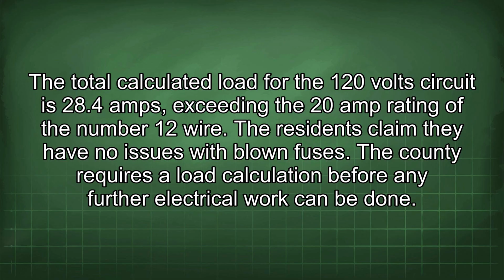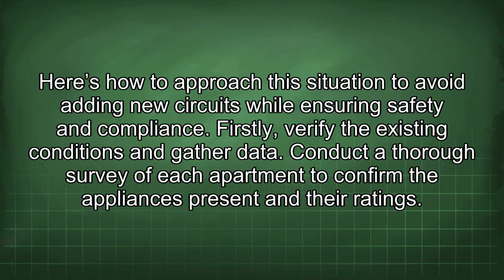The total calculated load for the 120 volt circuit is 28.4 amps, exceeding the 20 amp rating of the number 12 wire. The residents claim they have no issues with blown fuses. The county requires a load calculation before any further electrical work can be done. Here's how to approach the situation to avoid adding new circuits while ensuring safety and compliance.